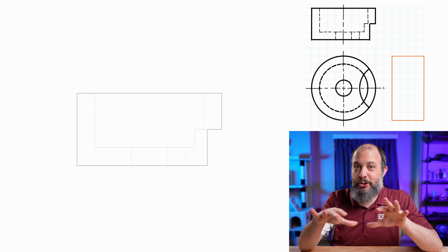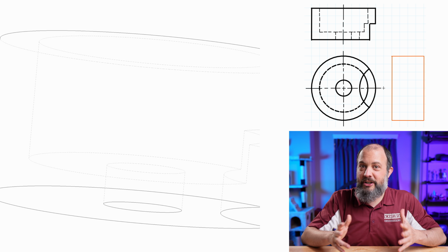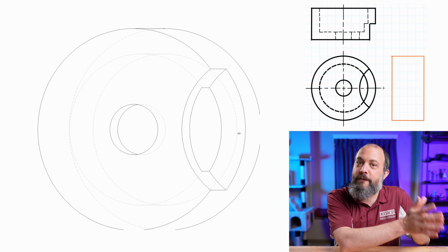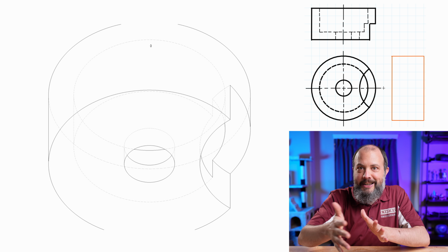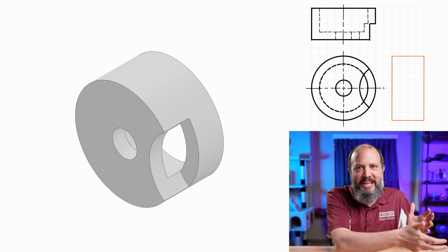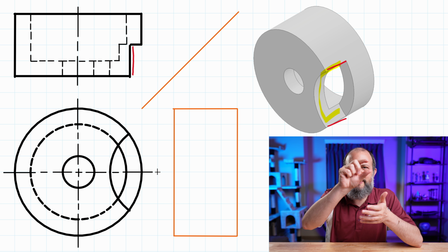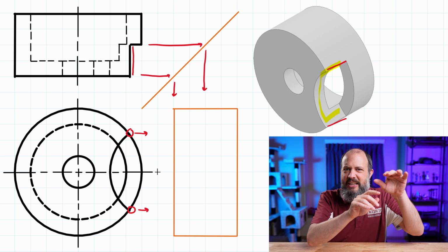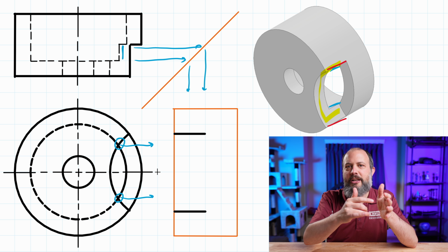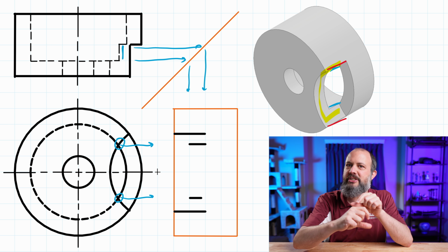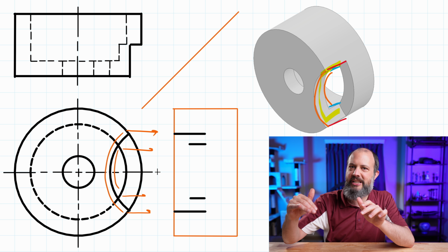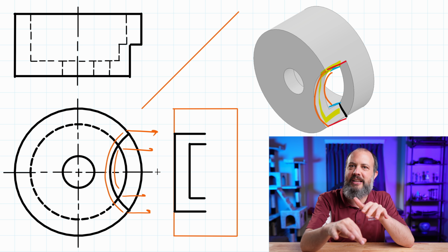What would this shape look like from the right? So if we want to draw the right side view, we're going to start at the right and work our way to the left so that we draw visible lines first, and then hidden lines will only be whatever is still hidden but not what's behind the visible lines. And the first thing that I'm going to draw is this sort of C shape. And the top is kind of hidden, but you can clearly see the bottom section where when you look at it from the right-hand side, of course you see that vertical sliver, but you see a very small horizontal sliver as well at the top and bottom where you're seeing sort of the inside of this solid piece.